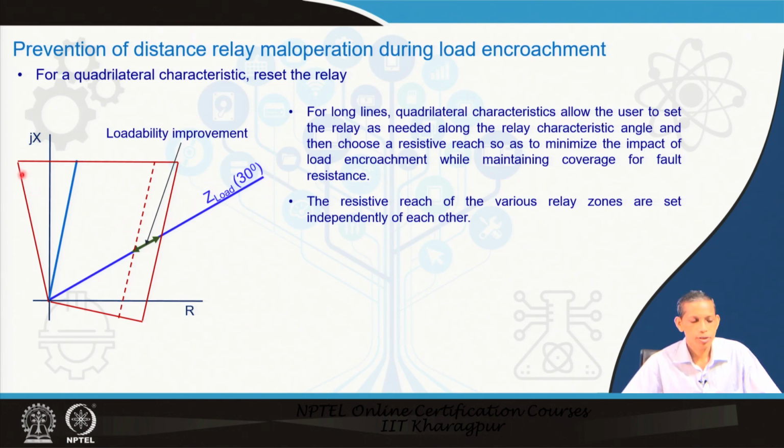In this kind of situation, if we expect to cover the RF for a zone 3 relay, but the relay characteristic is expected to have a load encroachment issue, we reduce the coverage and thereby exploit the advantage of this portion as the improvement portion. So, even if a load falls in this area, it will not go for a trip decision. We do not require this everywhere, only when there is a load encroachment issue.